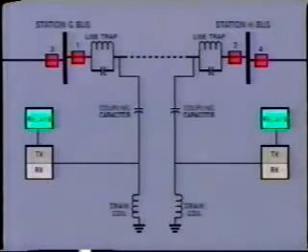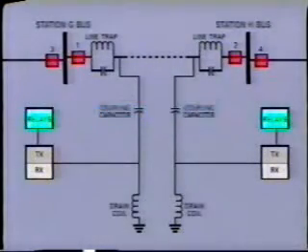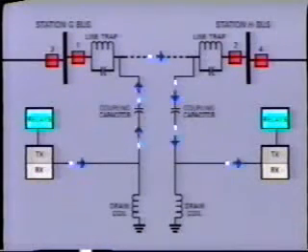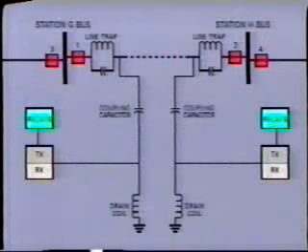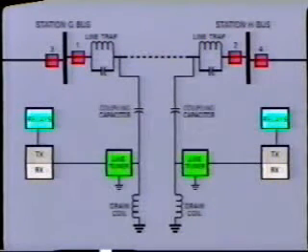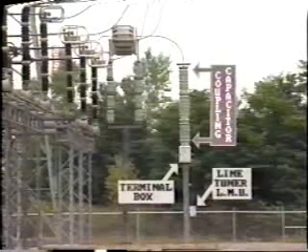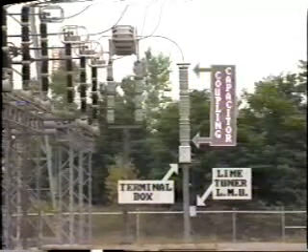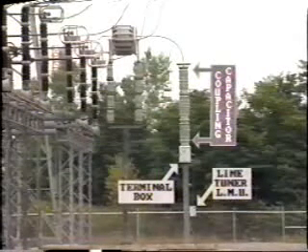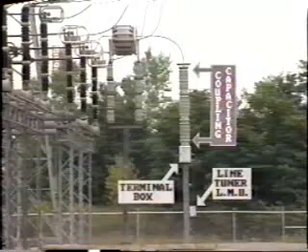So now, with our carrier equipment connected to the coupling capacitor, we have a low impedance path for the signal to flow into the line. We would like to have a yet lower impedance at the specific carrier frequency so as to reduce coupling capacitor losses. This is achieved by connecting a tuning circuit between the carrier equipment and the coupling capacitor. This circuit is often located below or at least close to the capacitor and is known as a line tuner or line matching unit, LMU.